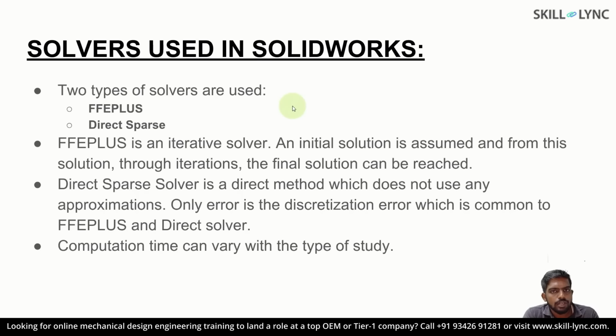In case you want to study more about how these solvers work, take a standard finite element analysis book and refer to solving a matrix iteratively and direct inversion. In case you are not worried about how the solver solves for the unknowns, just consider it as a black box approach and proceed with your simulation. Since both the solvers use different techniques, the computational time that each solver will take will vary between them.